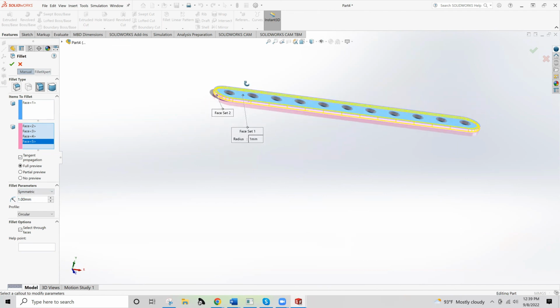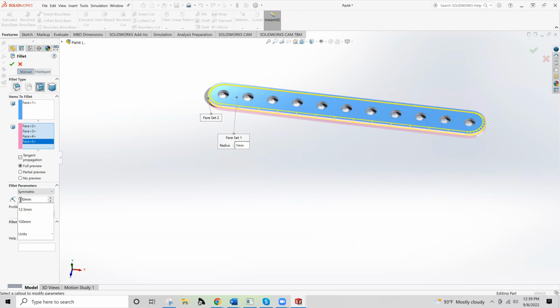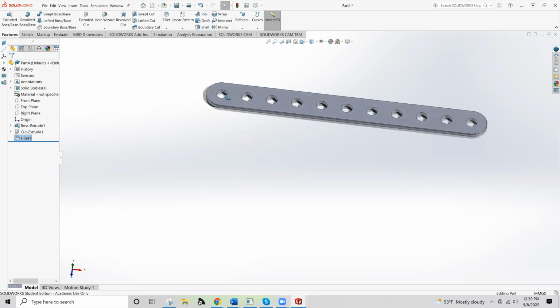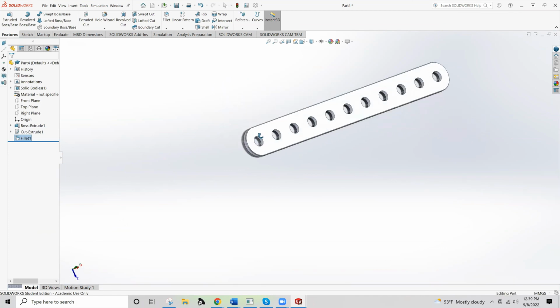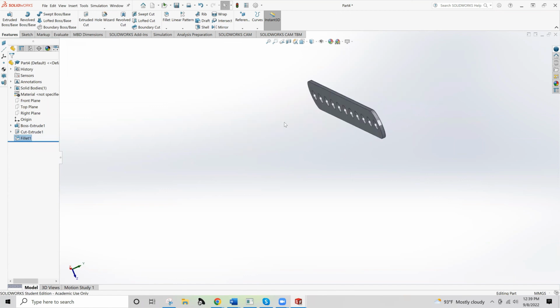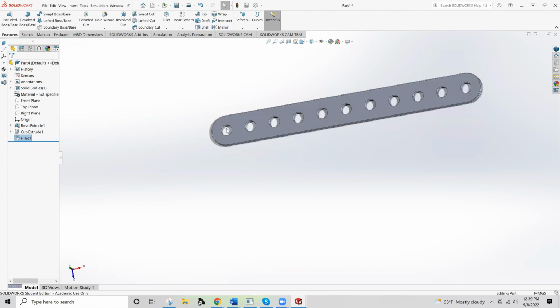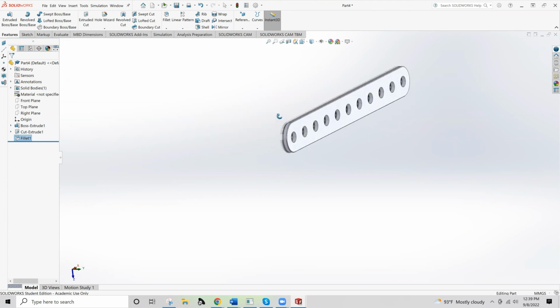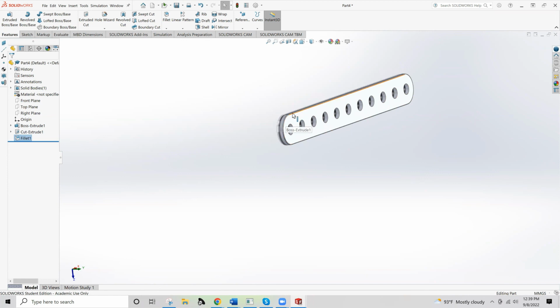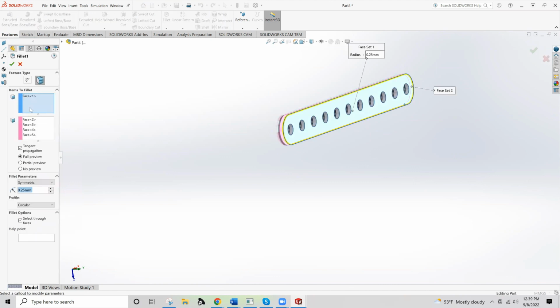It's doable, and it's going to need to be 0.25 to be like the actual part. It's going to have to be like a 0.25 millimeter radius. It can become very cumbersome to try and pick up those faces. Or if you only want it in specific instances, maybe you wanted that edge to be flat because of some constraint or design element in the part.